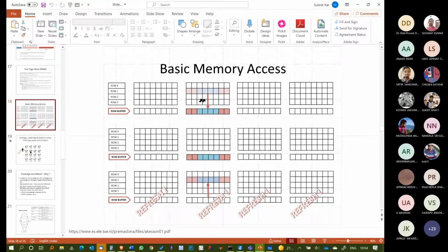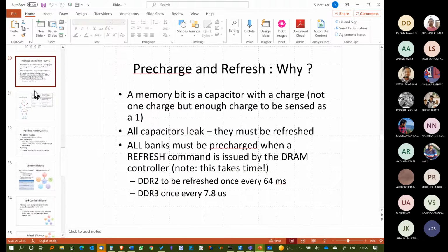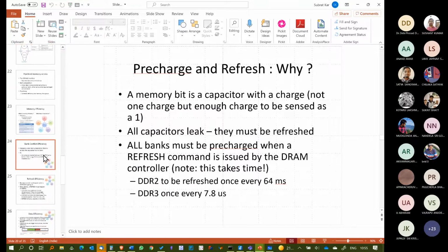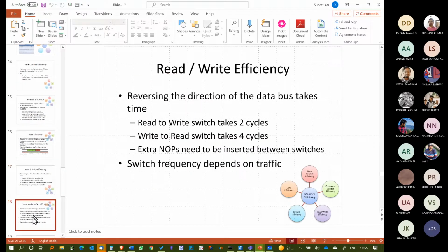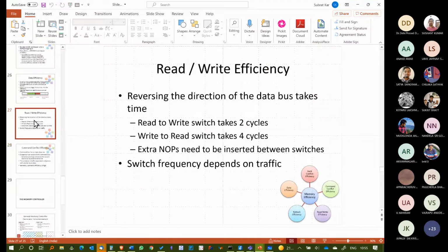Now, while it is doing that, the memory, being a DRAM, is actually refreshing this bank, this bank, this bank. Having read these sense amplifiers, it is then going to read this into the CPU and write it back to another bank. The number of cycles you need for this read and write is expensive. Let me see if I have those cycles somewhere. Okay, I have this.